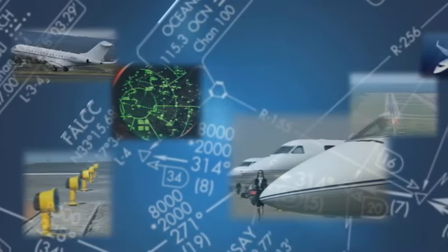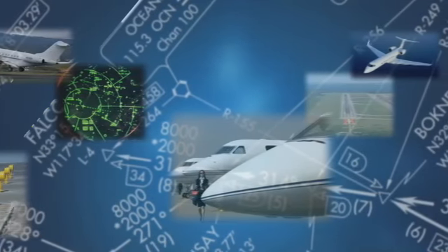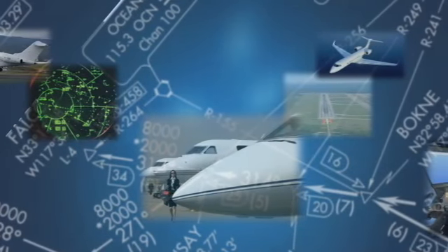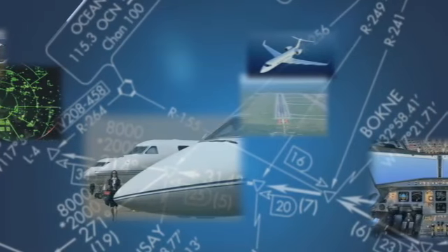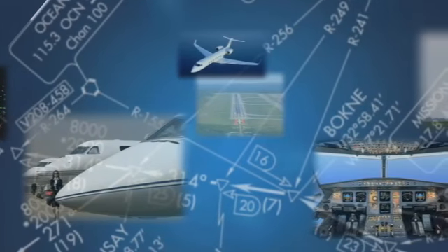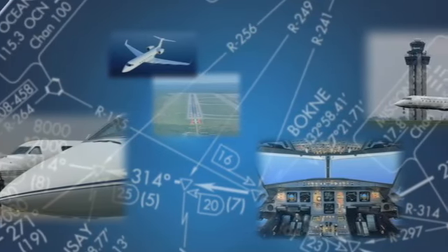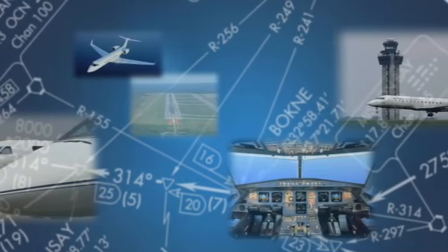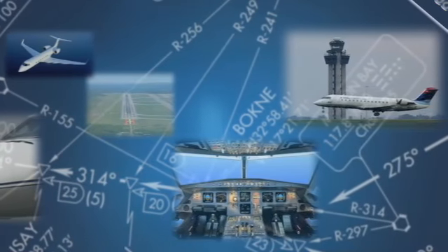Flight planning is an important activity of every pilot. A critical element is careful consideration of the airplane performance capabilities for the airports used for takeoff and landing. This is especially true for the takeoff, since the airplane is often near its performance limiting weight. Every pilot is aware that the length of runway available for takeoff significantly influences the maximum allowable takeoff weight. But what lies beyond the runway may be of equal significance.